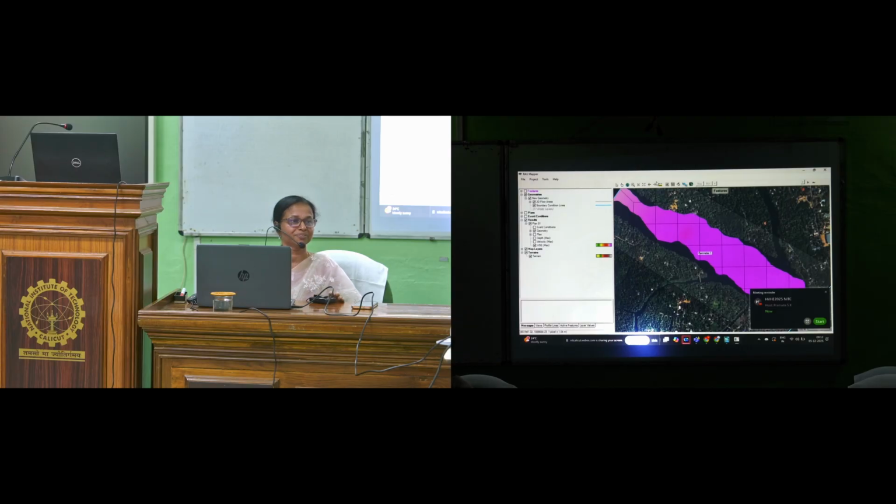So that's all. So you can see various options. Actually only one parameter here is the Manning's roughness coefficient. So that you have to vary to match with your historical flood inundation depth. You can use satellite data, compare with this one and then vary the Manning's roughness coefficient. The only one parameter here, not like the other hydrologic model. Here, Manning's roughness coefficient, you have to adjust and vary the flow depth. This is for 2D, and for 1D we have already distributed the tutorial manual that you can just go through.